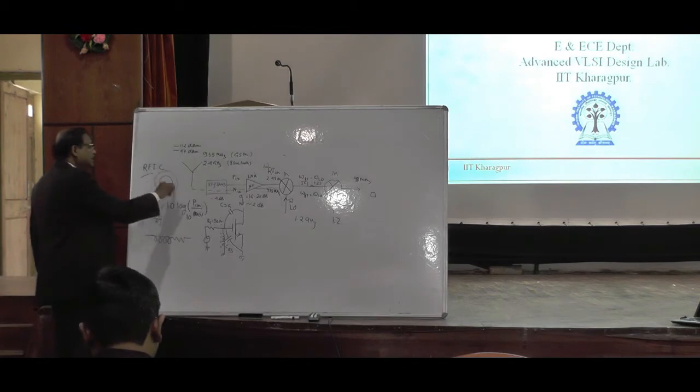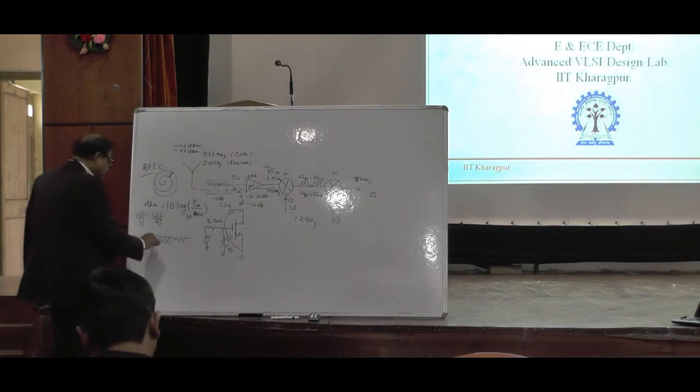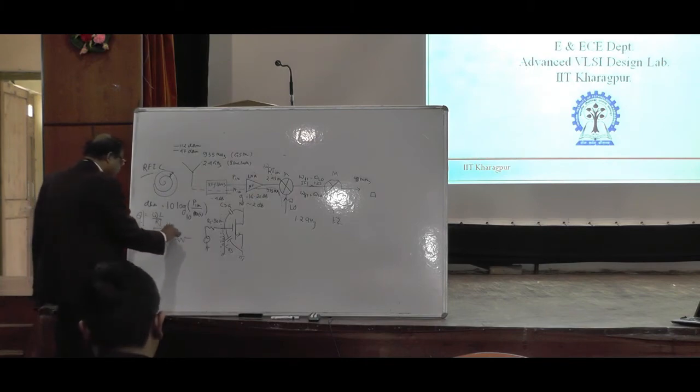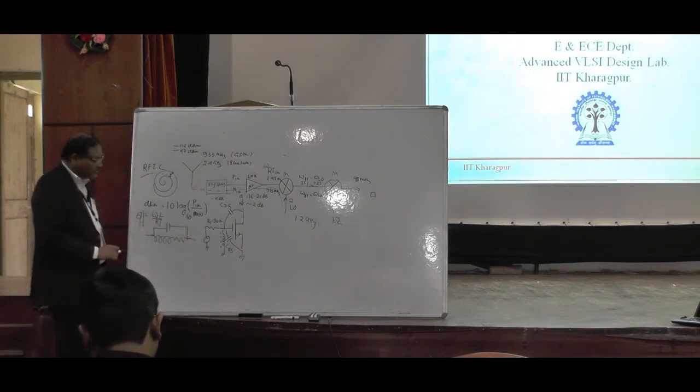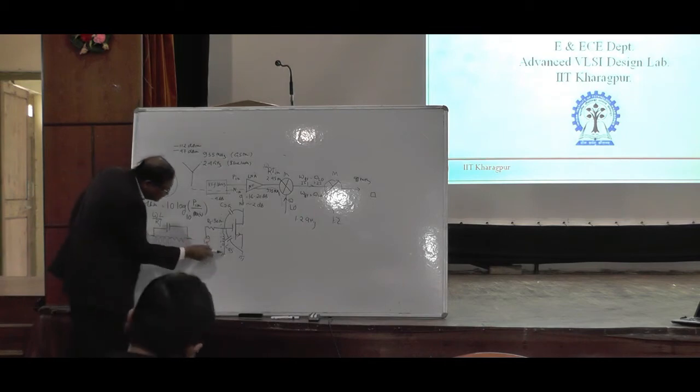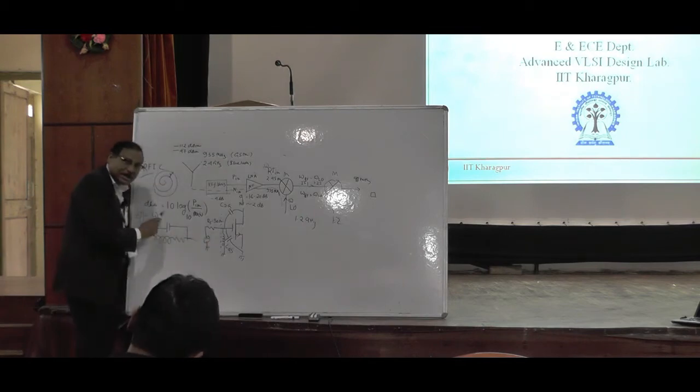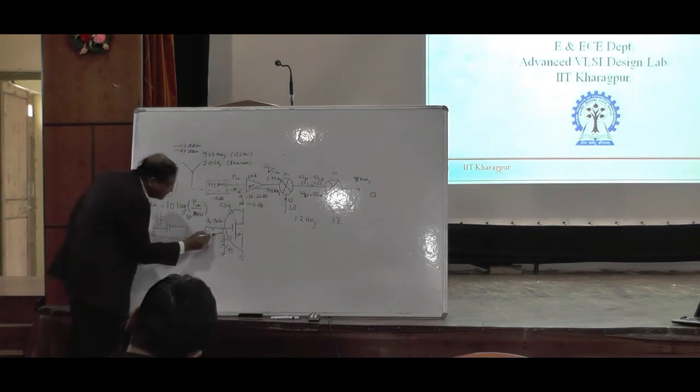A coplanar inductor is like that, so there will be a current flowing to the adjacent block. So there will be a capacitance. Yes or no? So those capacitances will come over. So think of it: when I am introducing an inductor, unknowingly I am also introducing a capacitor.